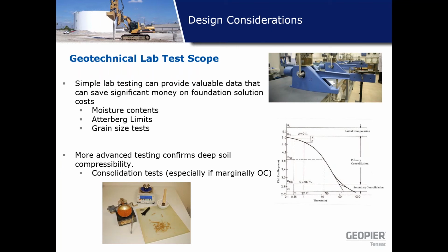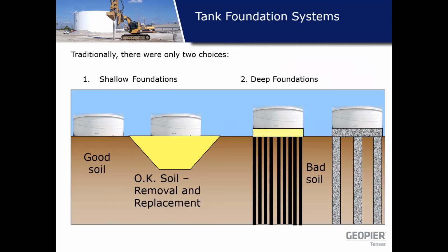We can also perform additional testing such as consolidation testing to understand the pre-consolidation pressure and overall behavior of the soil when it will be subjected to the tank pressures. So in the last few slides, we learned about design considerations. We learned about what we need to obtain from the field in order to design a proper foundation system.